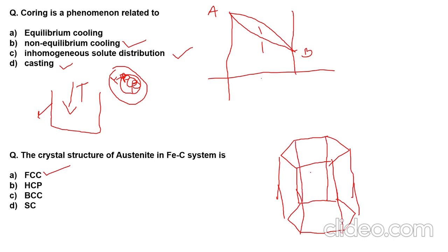This is your hexagonal unit cell. So on the top, which is the hexagon plane for your HCP, you have six atoms. And if you have seen a hexagonal unit cell closely, there are atoms at the center also. There are three atoms. One is at the center, and there are two atoms at the back, making such a triangular type of arrangement of atoms.